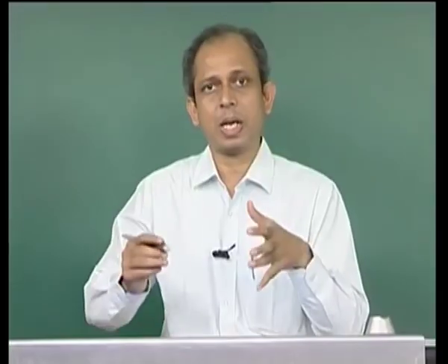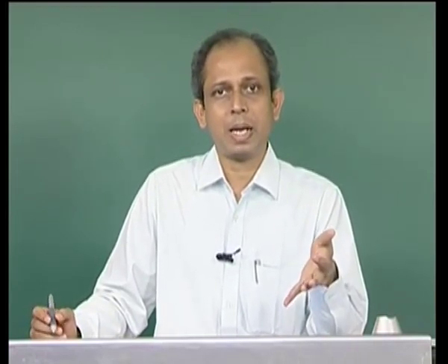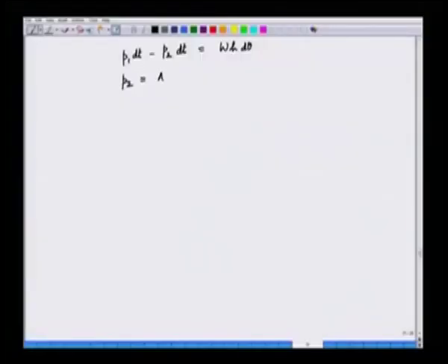So, P2 heat is dissipated to the cooling medium through the surface area. The cooling surface area is A, and the coefficient of heat transfer is K. So, we can say that P2 is given by surface area A into K into the temperature theta. So, that is basically the heat dissipated. So, we will be replacing that.